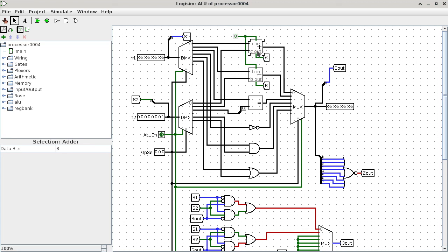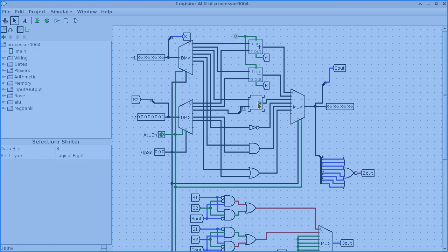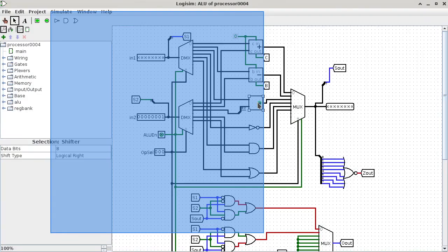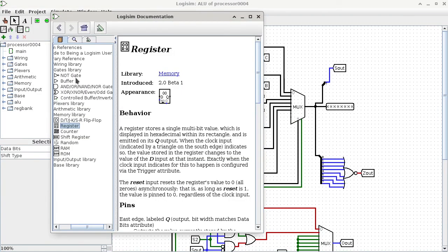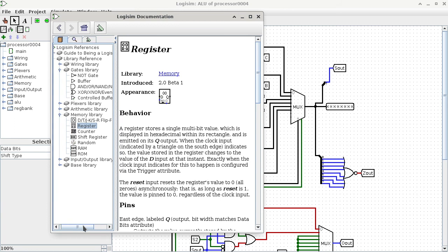So the ALU can add, it can subtract, it can do what we call a right shift. So we look at this thing here, and it says it's a shifter, and in this case, it's a right shifter because we see an arrow going to the right-hand side. So what is right shifting? So right shifting is a bitwise operation that is really useful. Unfortunately, most classes do not teach that in CISP360.